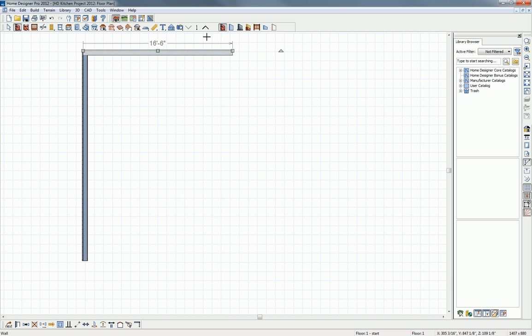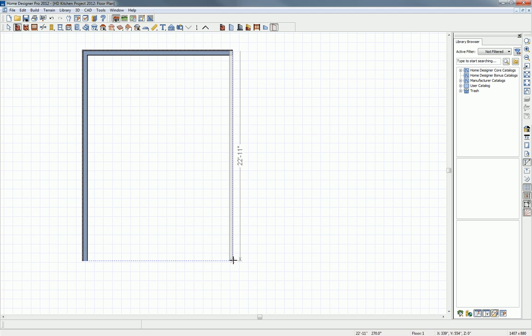Today we'll be focusing on one room, and the room is actually open to the living area. So I need to use my invisible wall tool to define this area so the flooring and the ceiling and everything is generated for us. We'll just drag that down and finish off the room with our interior wall. So you can use multiple walls to create one room for the space that you need. And then a living area is created and that square footage is calculated for you.